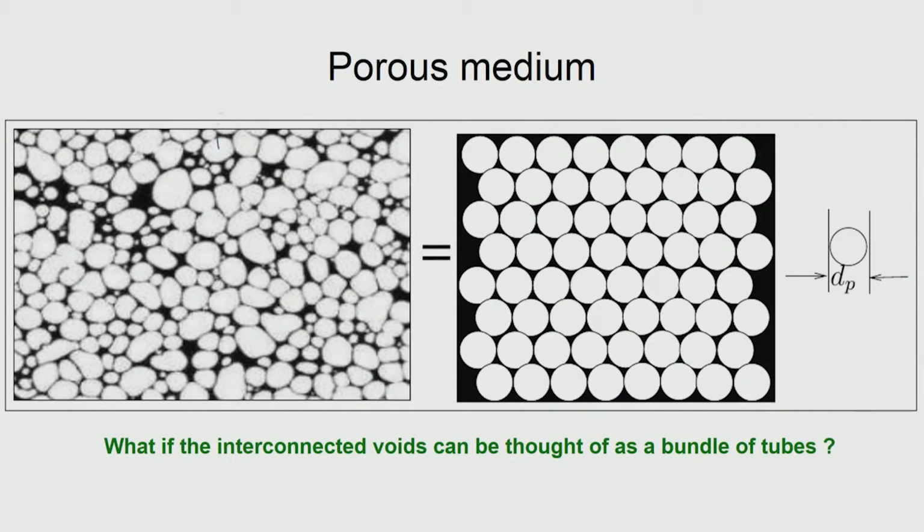And when we have a situation where a fluid is going through a porous body, what kind of an expression can we use? So, this is where, for example, we can see whether what we have learned till now can be applied. So, a very generic way of representing porous body would be like this, where you have got the white regions would be like, for example, the solid, and the black regions would be like the void. Okay. So, what this implies is that when you have a fluid that is entering from one end of the body, so it would actually go through the void which is interconnected and eventually come out. So, you could see that the path is actually tortuous, nevertheless it is available, so that the fluid can go through the porous body.